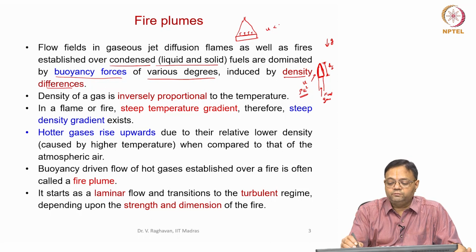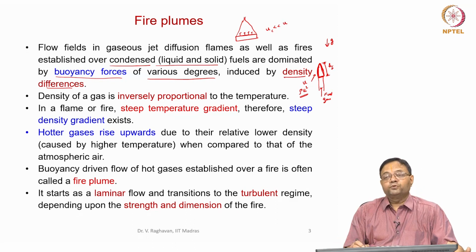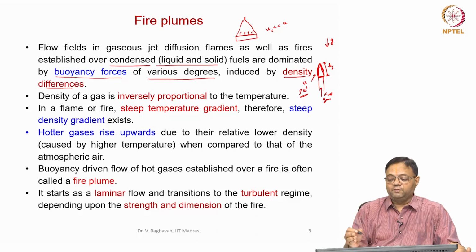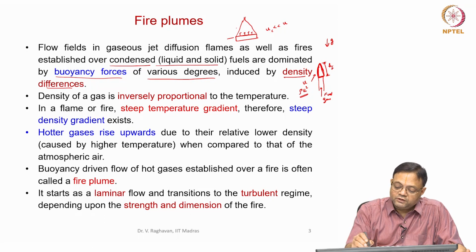So, the velocity for the condensed fuel, U_C, will be much less than U, which is the fuel gas injected at a particular velocity. So, the extent of this fire which is established over a condensed fuel surface is dependent on buoyancy forces.